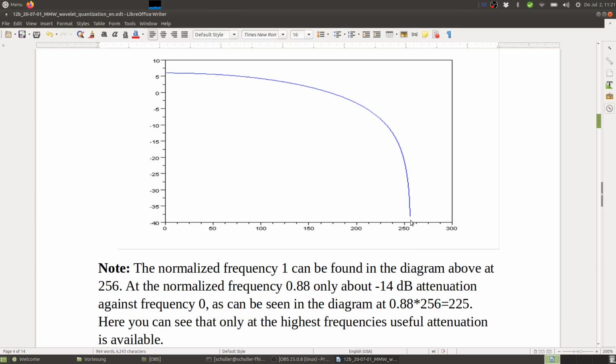And here you can see we don't have much attenuation. So the passband here is around maybe 6 dB plus. And if we want to achieve minus 40 dB, then we have to go from plus 6 to minus 40, which would be like 34. So here in this range, and 34 is already really close to Nyquist.